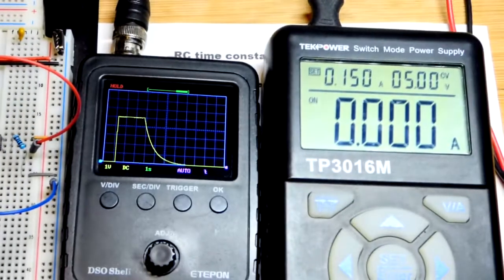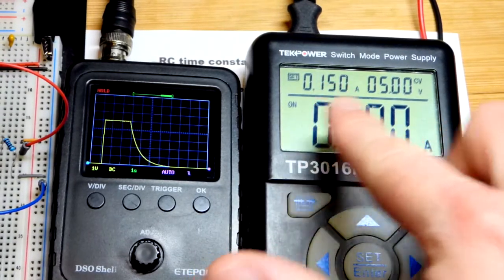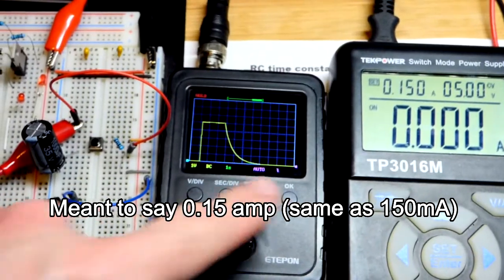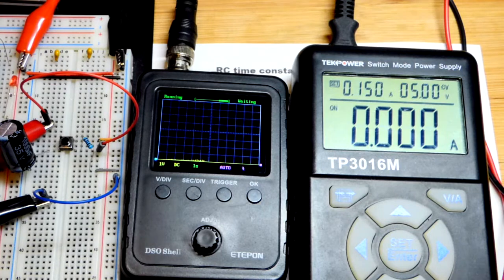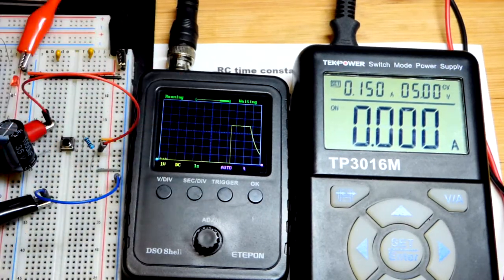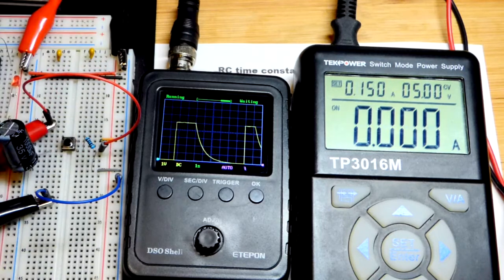Now, the power supply again. Usually I limit it to 20 milliamps or so to protect an LED. I have it up to 0.15 amps, and I'll show you why really quickly. I did have it at 0.09, I mean 90 milliamps, but that wasn't quite enough. But when I hit that button, it fully discharged instantly, and we should not have seen a charge on there. I wasn't paying attention, and there you can see we did not. You have to wait till it's fully discharged.